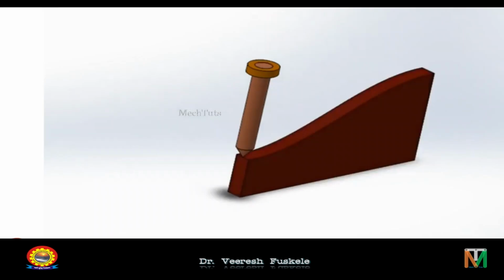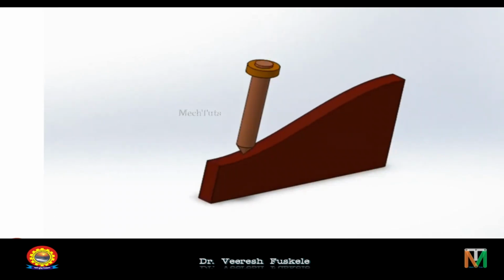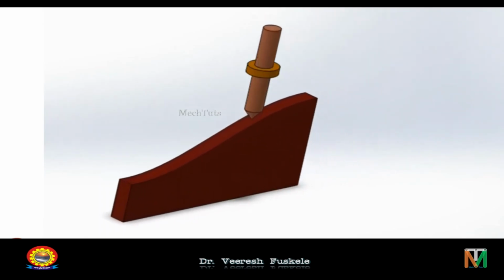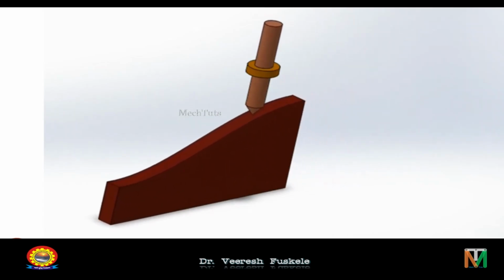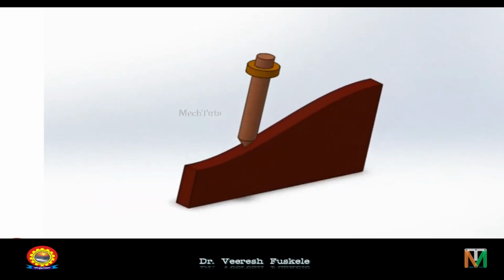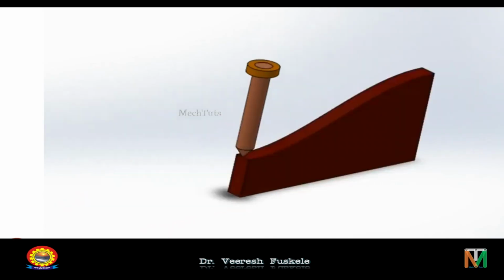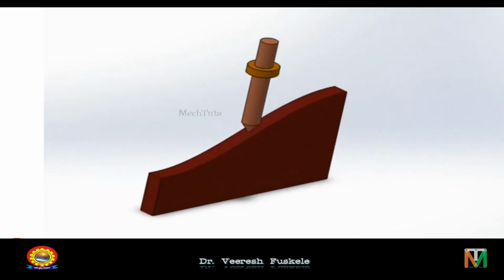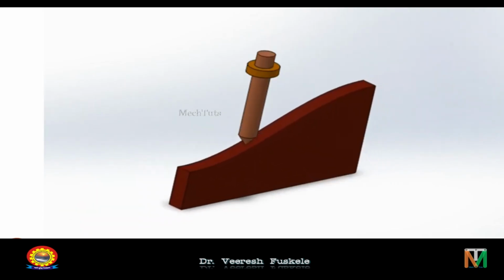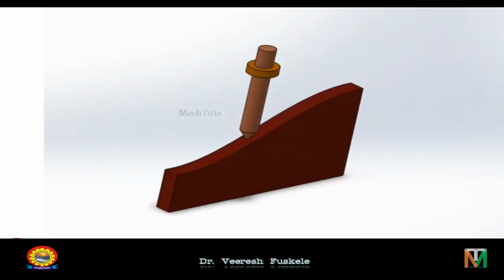Generally speaking, so far in this course, we have studied planar mechanisms which consisted entirely of lower pairs like revolute pair and prismatic pair. And now we will discuss the higher pair mechanisms, by which we mean that there must be at least one higher pair in the entire mechanism. Higher pair means the two links are connected either along a line or at a point, as seen in this case. One such higher pair mechanism is included in this topic and we start a discussion with what we call CAM and follower system.